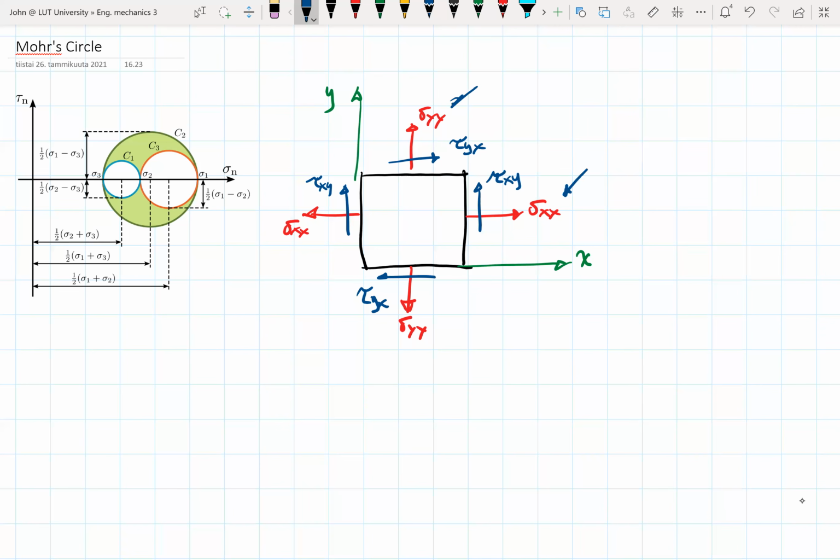It's important to recognize that, knowing just that principal stress in that direction, we could utilize this plane representation to find the other two principal stresses. This is pretty important. That's why it's a very nice simplification of the infinitesimal cube.